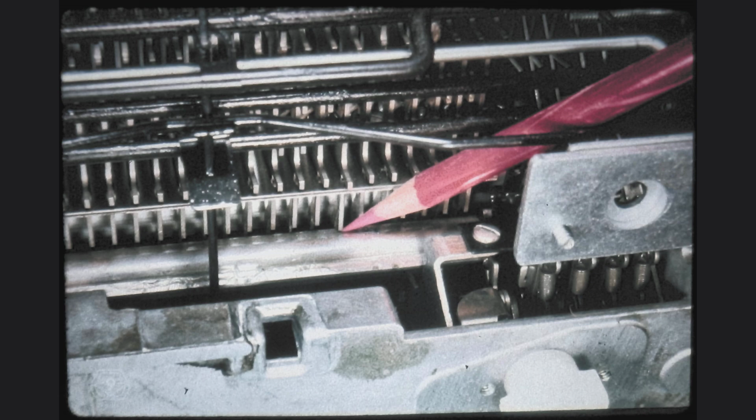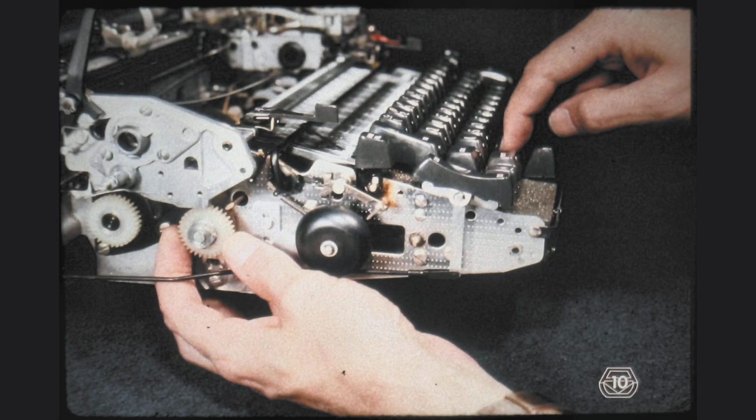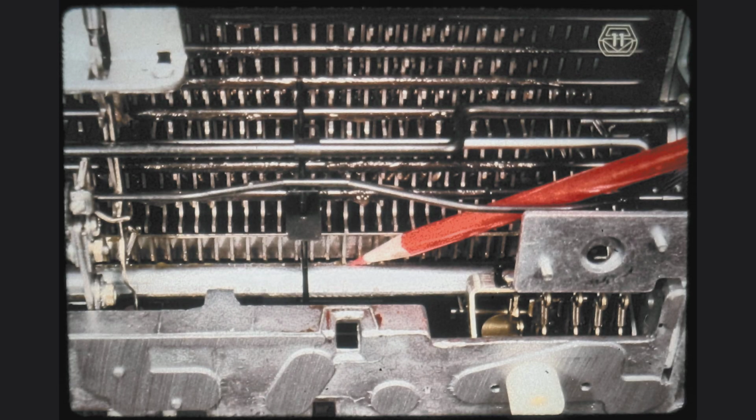Caution! If we inadvertently turn the filter shaft top to the rear, the small interposer latch spring will sustain damage. It is therefore very important that no matter what work we are performing on the typewriter, the filter shaft must always be turned top to the front. This is the same rule which applies to the hand cycle wheel on the operational shaft. The position of the filter shaft could actually lock the keyboard.